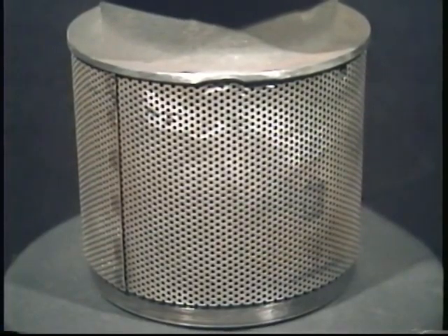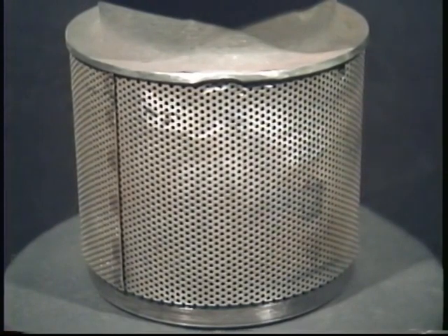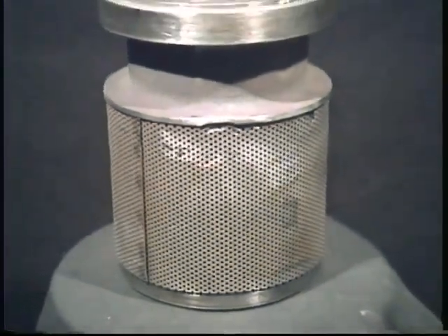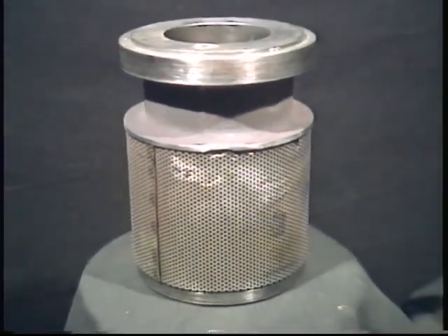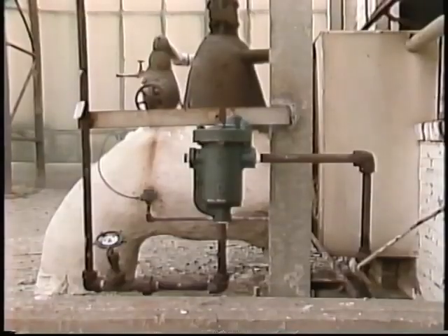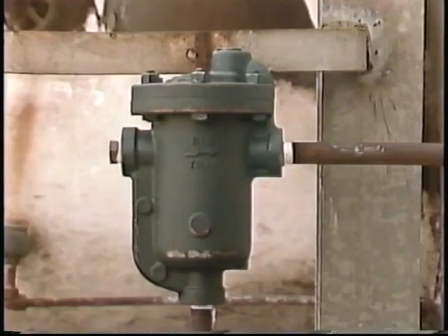Another common auxiliary device is a steam strainer, which is usually located at the entry to the steam chest. The strainer removes solid impurities, such as corrosion or scale products, from the steam before the steam is admitted into the turbine. In addition, the steam supply line usually has one or more steam traps at low points in the piping. The traps make it possible for the condensate to be removed without allowing the steam to escape.